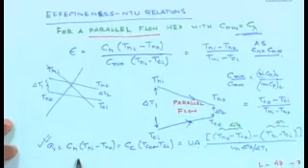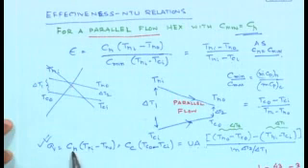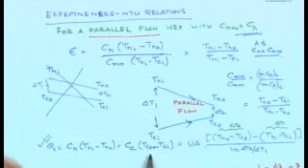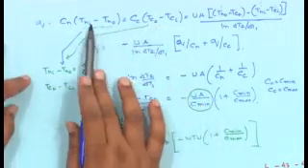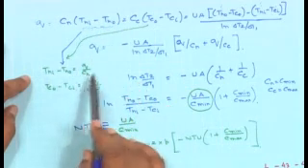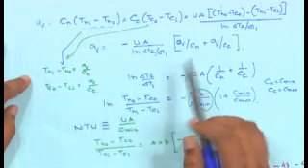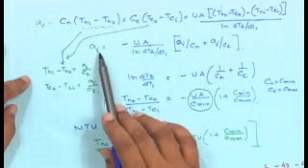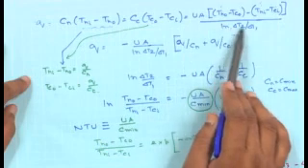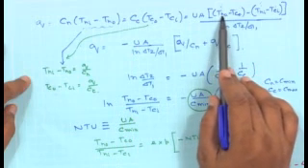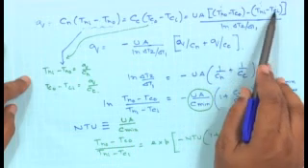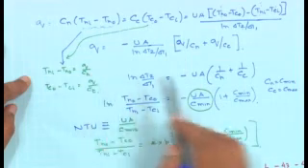This Q is also equal to CH, the capacity of the hot fluid, times the temperature drop of the hot fluid, and CC, the capacity of the cold fluid, times the temperature rise of the cold fluid. And this is simply the definition of LMTD, which we have seen before. So from these two relations, I can write the temperature difference of the hot side is simply Q by CH, and the temperature difference of the cold side is simply Q by CC. Since Q is equal to this, Q can then be equated to UA by ln(delta T2 by delta T1), where the temperature differences Thi minus Tho and Tco minus Tci can be expressed in the form of Q by CH, as I have shown before.